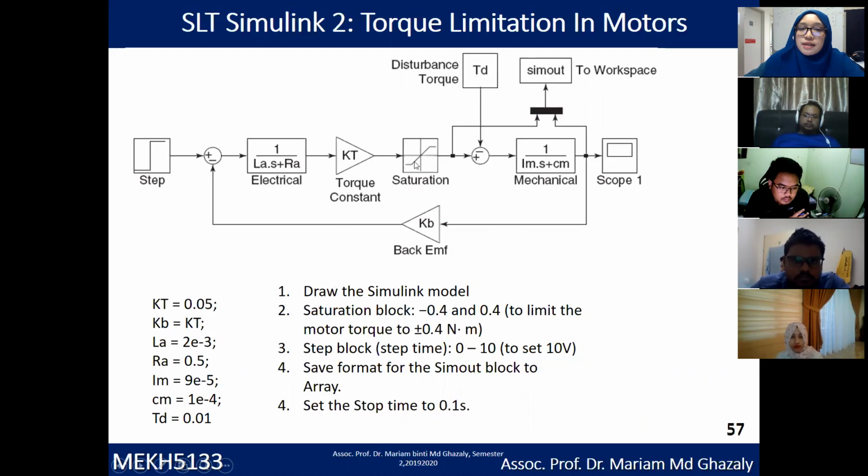Okay, so this one is for safety reason. So saturation, we normally put it in the beginning here before we go to the actuator, which is the mechanical part.